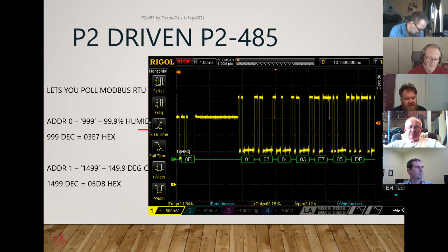The trick we talked about last week is really to just use the smart pins to mirror, so that you get the differential drive happening between an adjacent odd and even pin. And from that point, you can use anything, whether it's just a smart pin mode or something like an FDS or a similar kind of object to do the transmission.